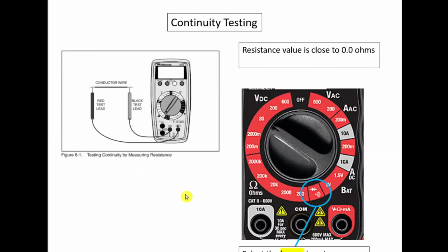All right, now we didn't talk about this, but I want to make sure to cover it. On your multimeter there is usually a section down here that has this symbol that looks like a speaker. That speaker is basically a buzzer on the multimeter. This is a way to check continuity. So if I took a solid wire and I want to make sure it's not broken, another example would be a fuse. But let's stick with a solid wire here.